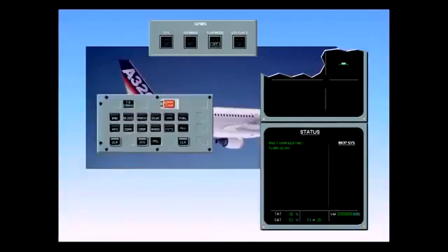The other message states that the flaps will be slow. When a SFCC flap channel is inoperative, the flaps are still available, but they will move at half speed. If the 2 channels of one SFCC fail, both slats and flaps will operate at half speed.